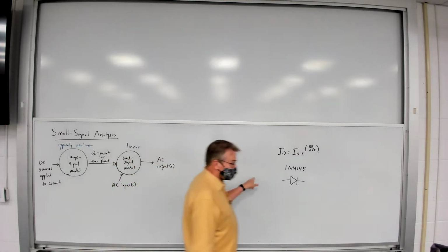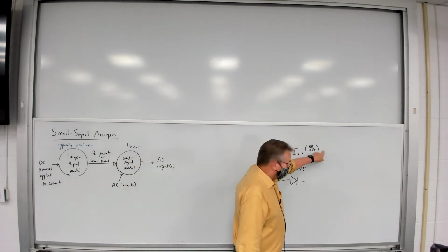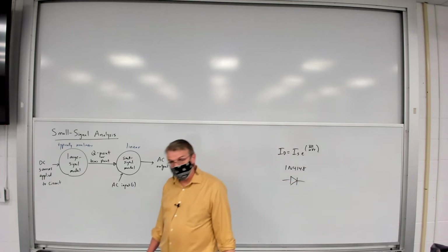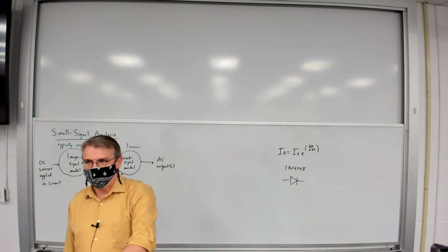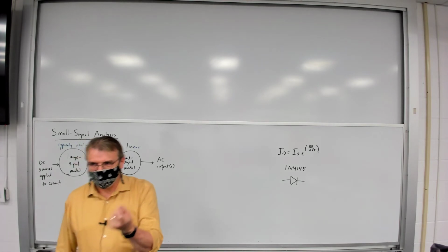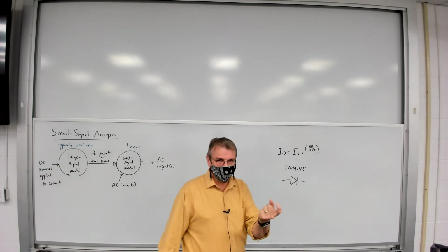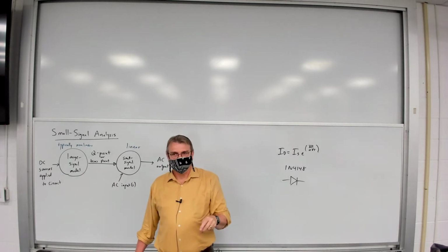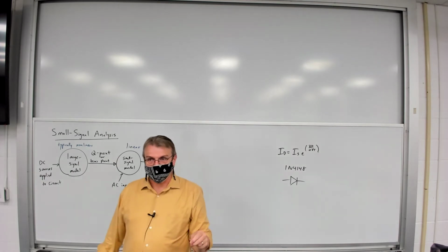Also, I should point out that these equations and the simulations are not going to match, and what you measure in the lab is not going to match either, because all components have tolerances. The LTspice model is basically an average or a mean of all the different characteristics of those diodes.